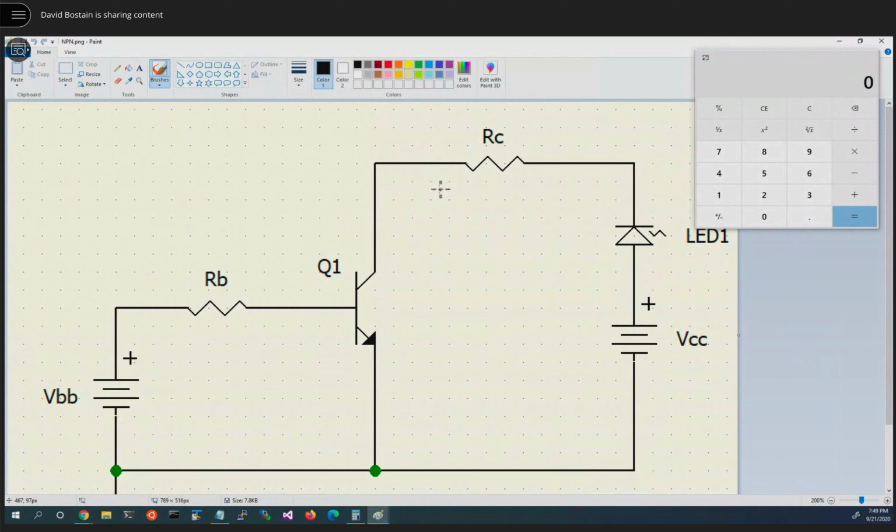Okay, so what we're going to do is I'm going to tell you that you have some standard parts, meaning you have a standard transistor, you have a standard LED. We're going to use the minimum wattage resistor we can use that is safe to use, and we're going to use the value that's closest to the computed value, meaning that if it only appears as a 5% and it's closer than it would be as 10%, we've been driven to 5% resistors.